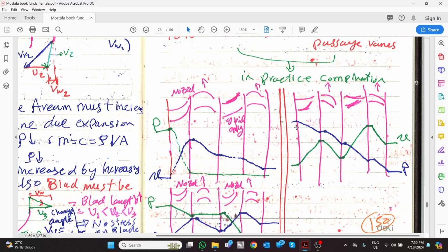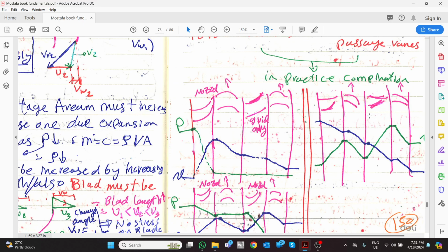The pressure is reduced here, changing from pressure energy to kinetic energy, then it still has some pressure, and we take the pressure again. So there is kinetic energy transfer, and I am also taking nozzling, from the pressure energy to kinetic energy. Then nozzling again, from pressure energy to kinetic energy. Then at the vane, from pressure energy to kinetic energy, plus transferring kinetic energy from the fluid to the vanes itself.